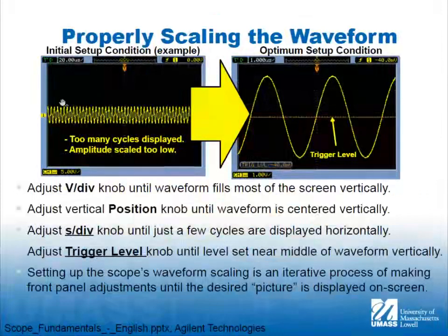So this is hard to read. This is not hard to read, right? So you want to get it scaled so you can see about a wave or two, and you see full scale so you get as much resolution as possible, right? You don't want to jam it all into one place. And that's what these knobs do.